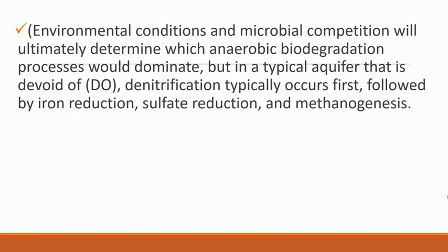Now, environmental conditions and microbial competition will ultimately determine which anaerobic bioremediation process will dominate. But a typical aquifer is devoid of dissolved oxygen. Denitrification typically occurs, followed by iron reduction, sulfate reduction, and methanogenesis. Okay, so in the environment, especially when there is no dissolved oxygen, you will begin to see processes like denitrification taking place, iron reduction, sulfate reduction, and then the production of methane.